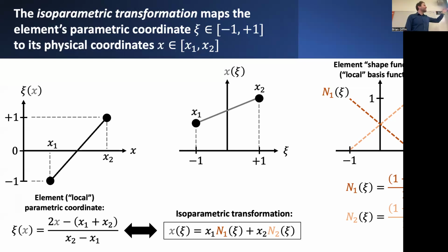So in the case of this one-dimensional problem, the shape functions are really just these two basis functions associated with the two endpoints of this particular element that I'm looking at. All right. So if I wanted to represent the interpolated displacement field expressed in terms of U1 and U2 defined over the length of this element, I could plug in U1 times N1 plus U2 times N2, and I would come up with some interpolated representation for the displacement field over the length of the element.